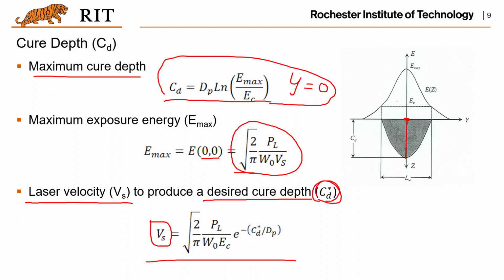And that could be a question in the homework or exams. That is, given a cure depth, tell me what the laser scanning velocity is.